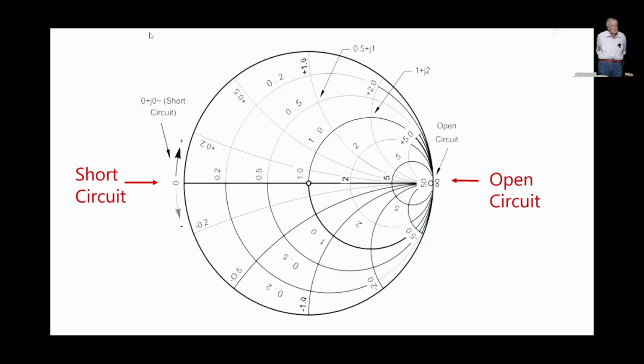So if you try to realise a network and you find yourself down in that end, then the network's not realisable. It means that the actual values will change so quickly that it's just not practical. So you've got to try and work with the Smith chart in the areas where you can logically plot a value.